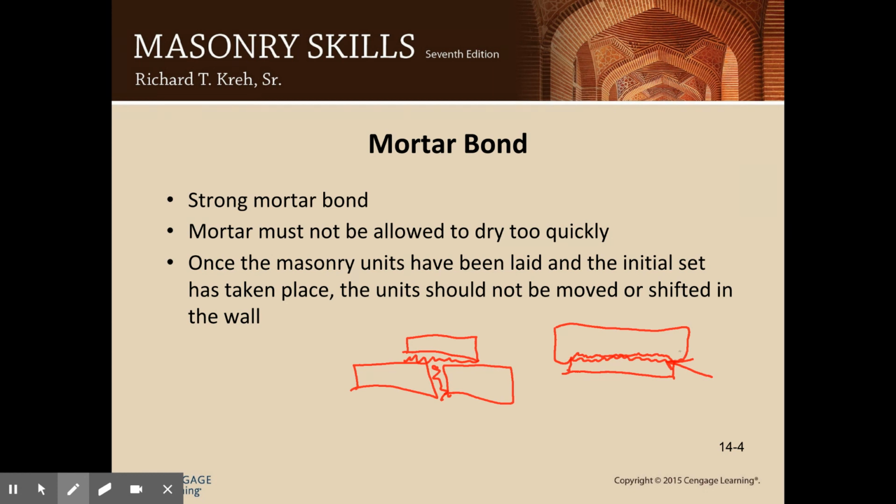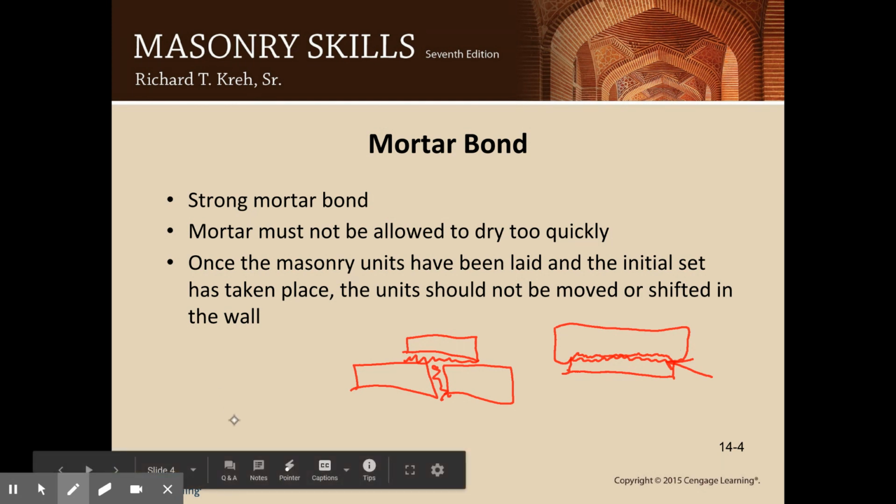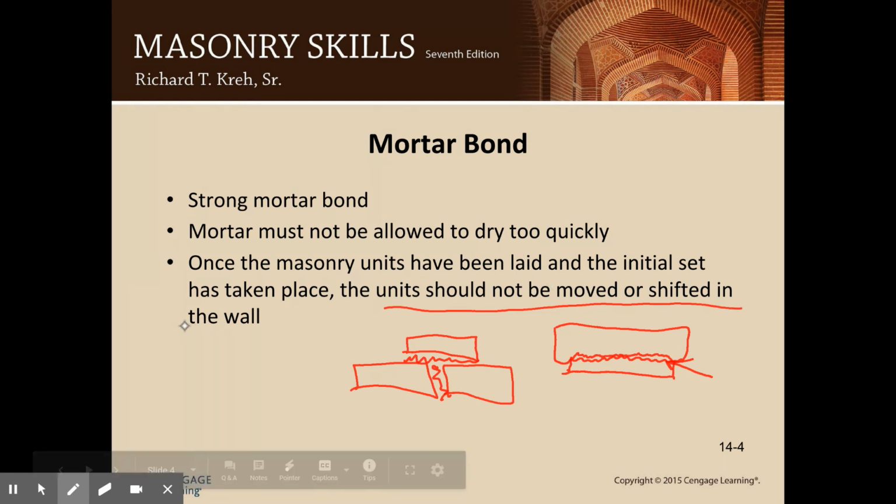Once you lay your brick and it starts to get thumbprint hard where you're ready to strike your joints, you should not move or shift the wall. If someone hits the wall that you're working on once it's starting to set, you're going to have to reset the bricks because the bond will be broken.